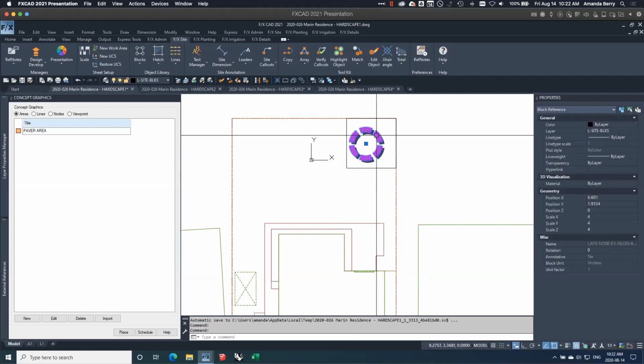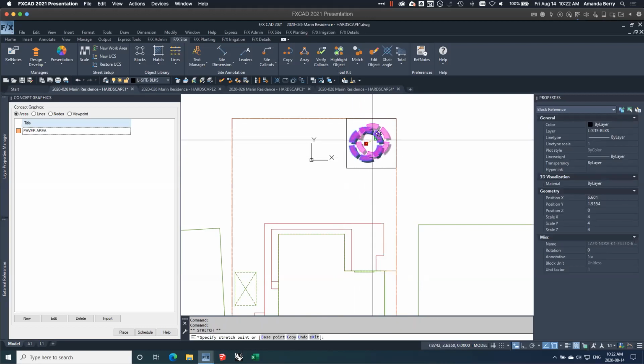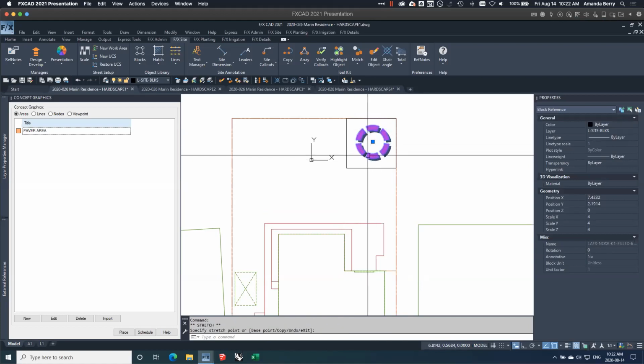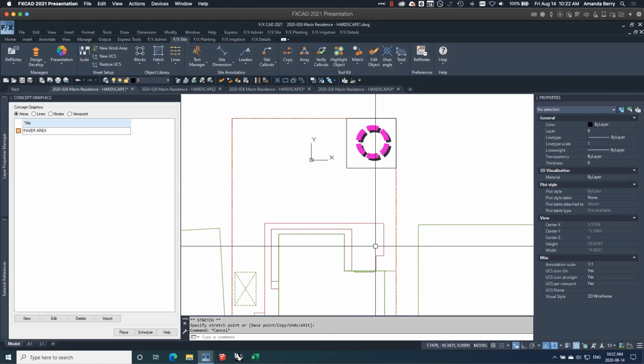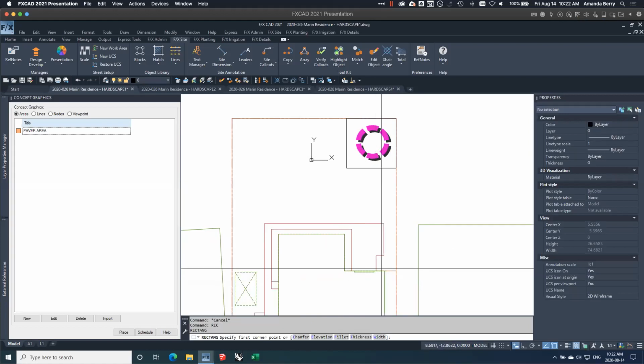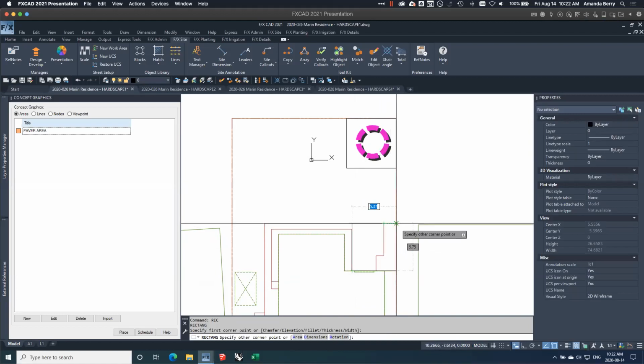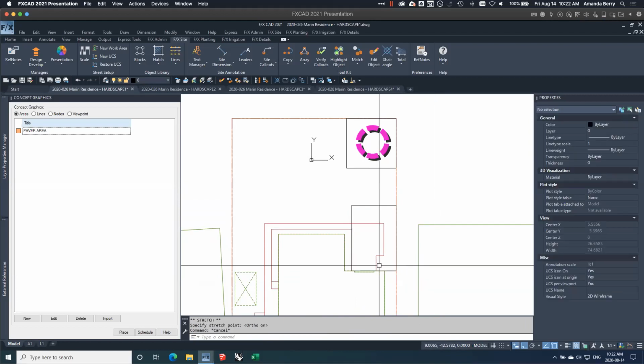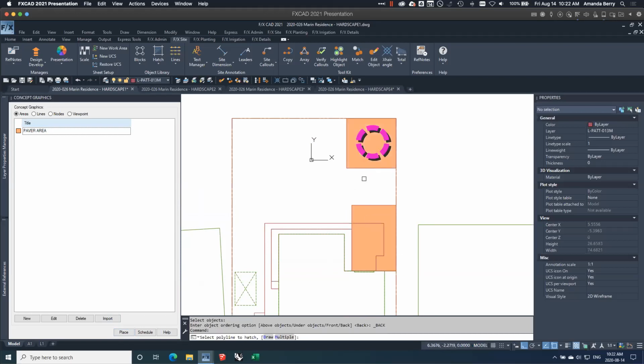And click that in. And now, because this is a movable object, I can move this around, play around with it as I start to refine this drawing and this concept. I can say maybe do a rectangle in here. I'll snap down here, snap over, but maybe I want to extend that, so I can hit F8 for ortho and pop that up a bit. So I've got 2 paver areas for my kitchen and dining area and my lounge area, and I can grab that paver area and just place it in, just like that. It's nice and colored, that color that I want it to be.